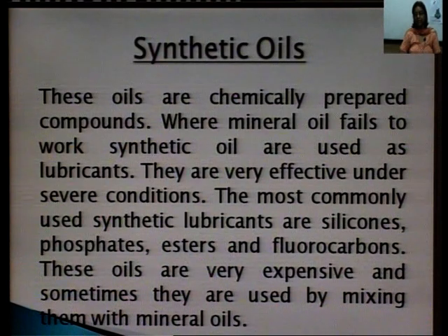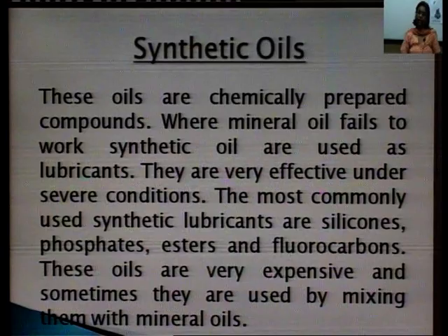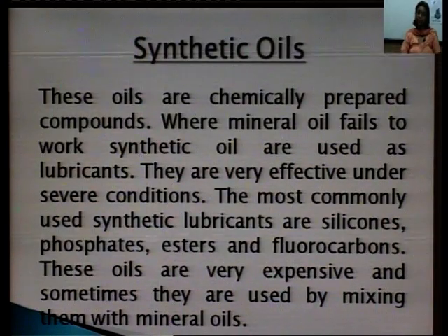These oils are very expensive and sometimes they are used by mixing them with the mineral oils. Means we can mix these synthetic oils with the mineral oils so that their cost is reduced and the properties of the mineral oils are improved.